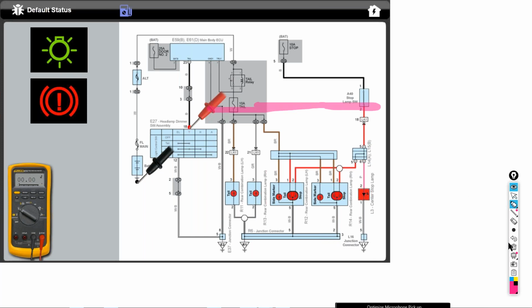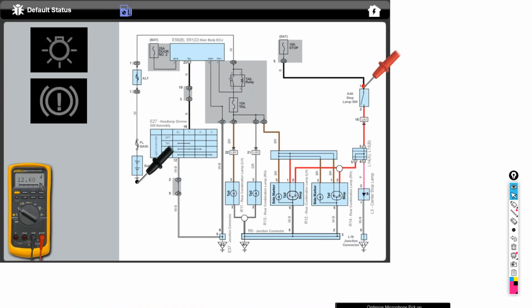Let me go back here. Move the voltmeter over here. You see you've got 12 volts here. I'm going to turn the stoplights off. We've got 12 volts to the switch, 0 volts after the switch, 12 volts when it's on. So they can show them you've got power side switching, manual ground side switching. So there are some of the different ways you can work.